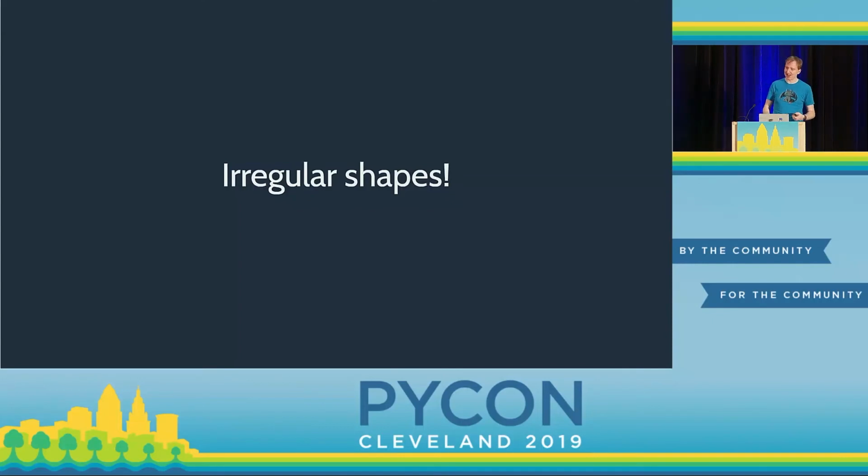And so you have to go back and modify that software to make it understand that there might be edges in here. And rather than going around the edge of the square, you have to work out where the edges are, bring that in, and then it basically works out the outer perimeter of that part of the model, and that's where it builds its wall and builds its solidity. The nice thing is the driving programs for the milling machines do also take STL, so I can still use that part of my code again.